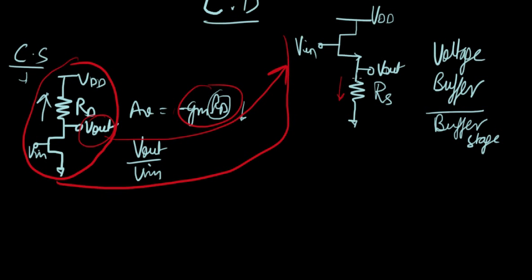Alright. So V out is given by what? Before we do that, let's first plot V out, for an example, to have something to start with. So we start increasing V in from 0. This MOSFET doesn't turn on until V in has reached VTH. So V out will be 0 until VTH. Let me grab a different color here.